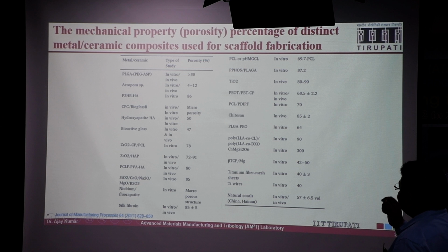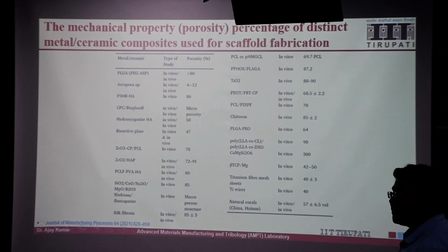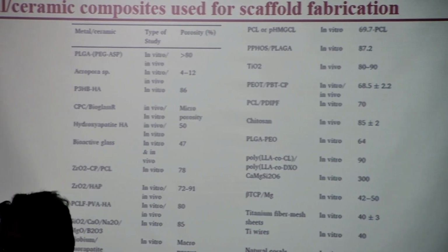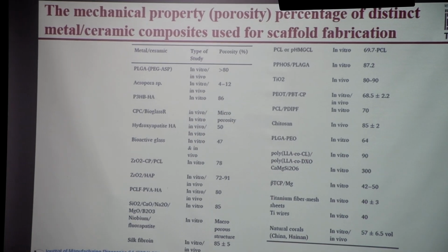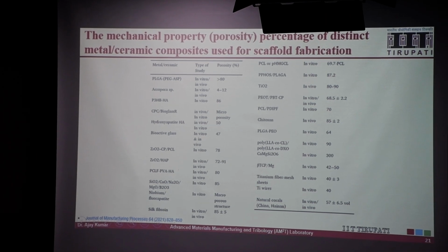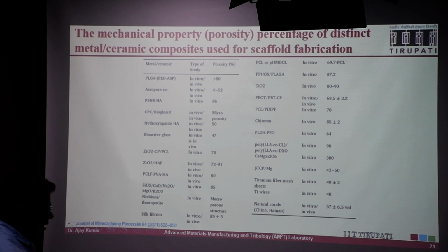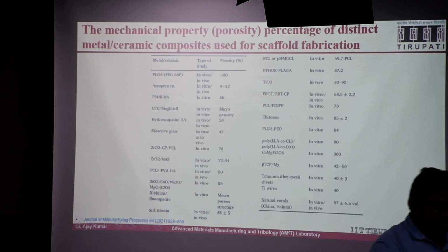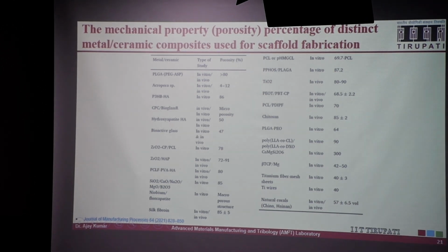Another thing is the porosity percentage. Especially in these 3D printed, additive manufactured materials, porosity is the challenge. If you have used some of these materials, you can just cut the sample which you have printed and check it under the microscope, and you will see a lot of void pores there. That is why people are afraid to use these techniques in critical applications.